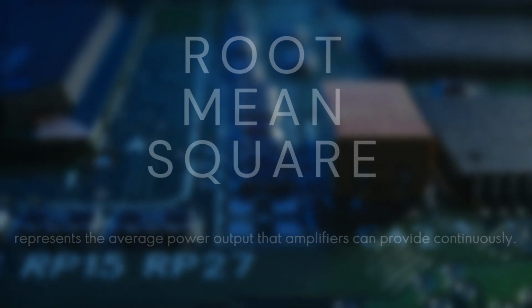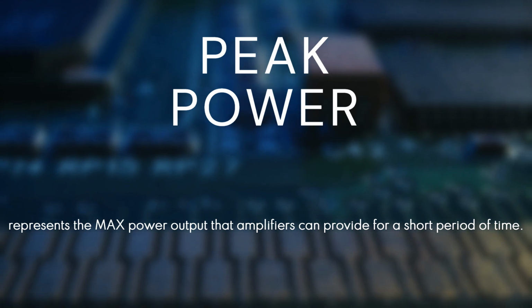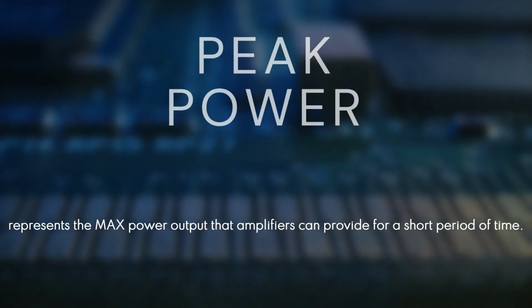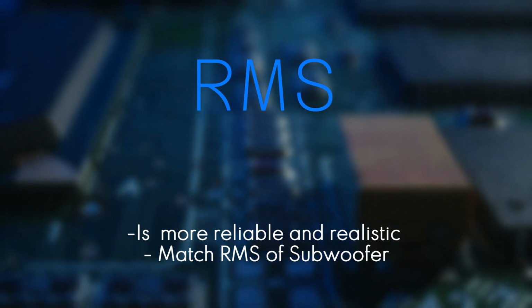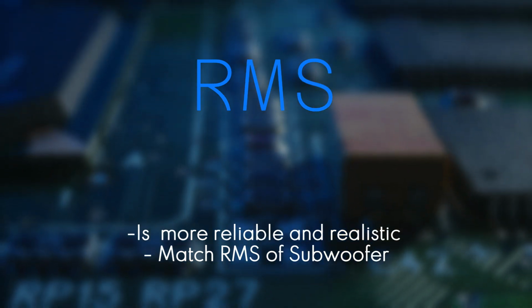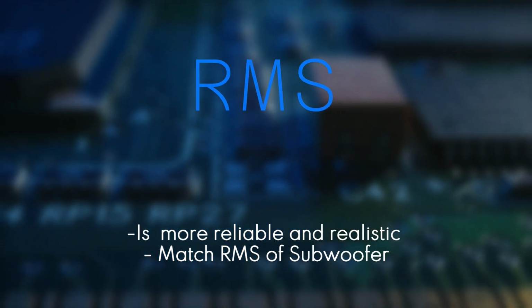Peak power, also known as max power, represents the maximum or burst power that an amplifier can produce for a short period of time. RMS power is more reliable and realistic than peak power, and it should match or exceed the RMS rating of the speakers or subwoofers that you are wanting to connect to the amplifier.